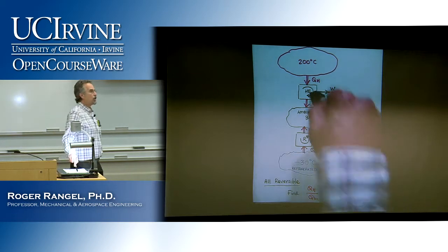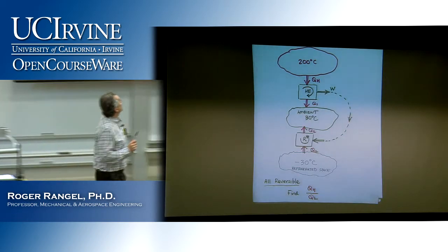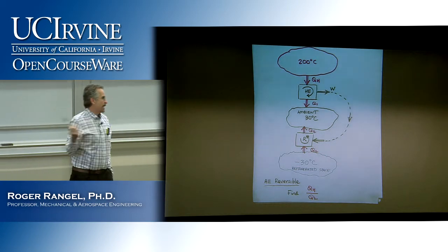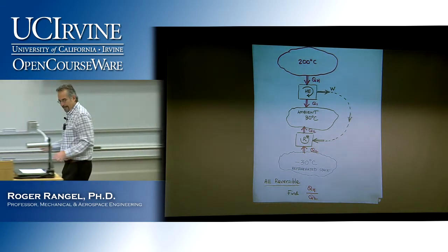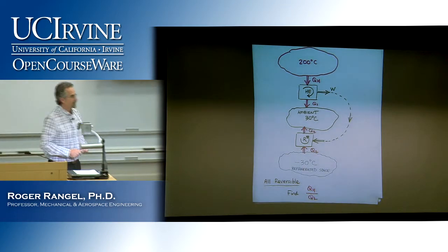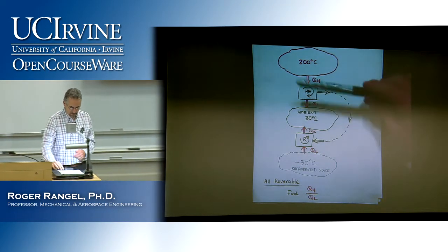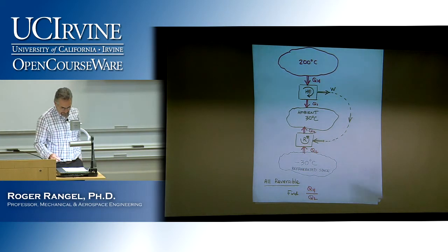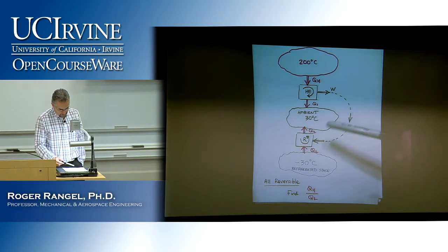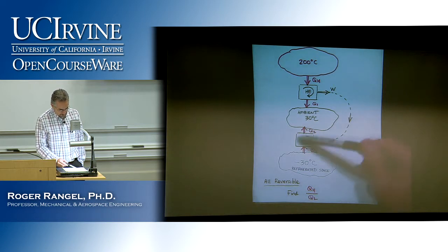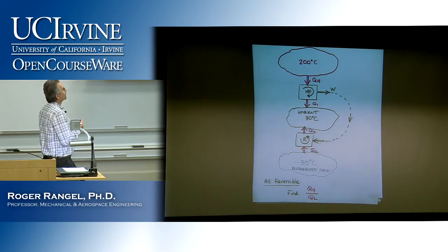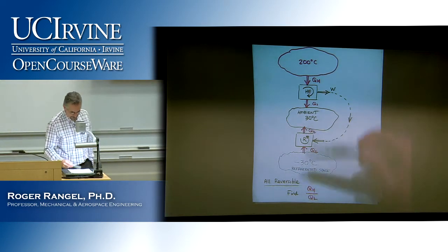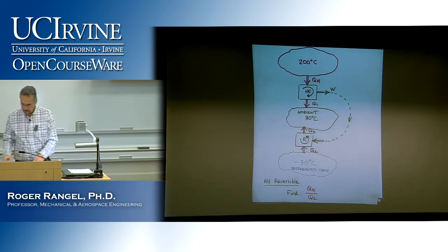If it's a Carnot heat engine, all I need to know to find the efficiency is the temperatures of the reservoirs, and I have them. I have the temperatures of all the reservoirs, which is nice. So I can find the efficiency of this heat engine. And could I find the coefficient of performance of this refrigerator? Yes, again, because it's a Carnot refrigerator and I have the temperatures. So I can do those two things.